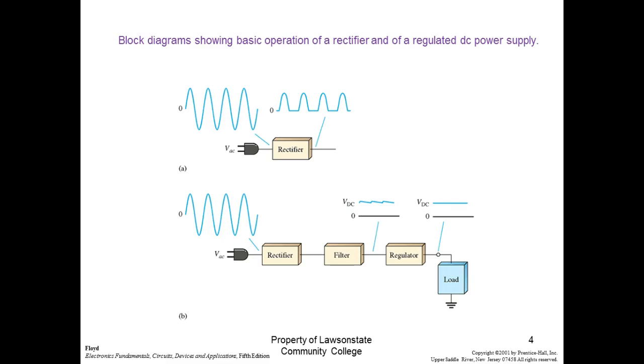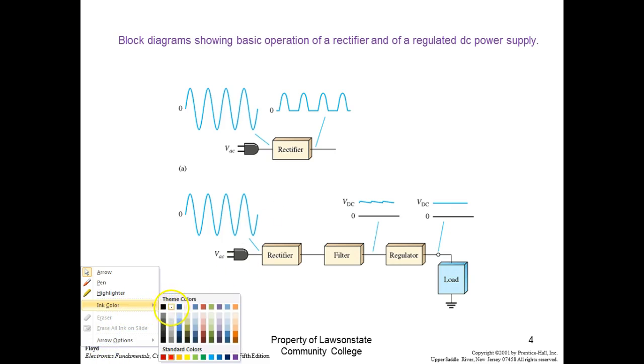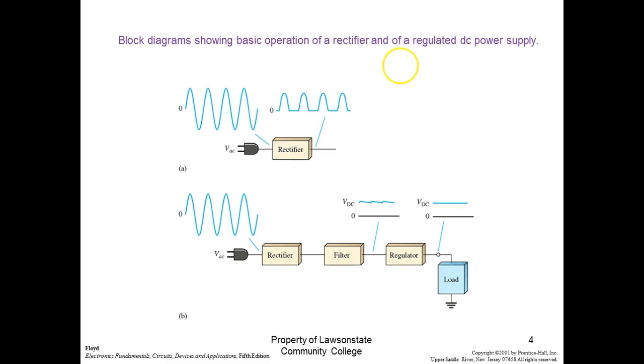So we came over here and we put together this little tiny power supply. Our power supply is just a tiny bit more complicated, but not much. So we could do it this way. If we bring 120 volts in, what DC would we get out? First of all, I'm going to say 120 volts, and I'm going to figure VP. So I'm going to take 120 volts and divide it by 0.707. And what do we get?